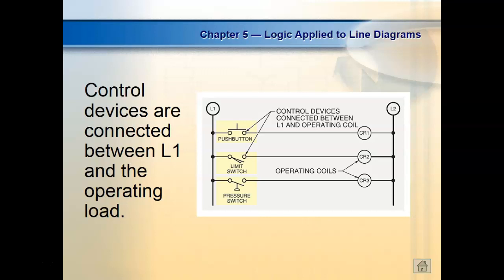So a normally open push button goes above the terminal symbols, and normally closed push buttons go below. And they should touch. So normally closed should touch. And then normally open should not touch the terminal symbols. And like I said, when this guy draws the normally opens, he just leaves a little air gap right there.